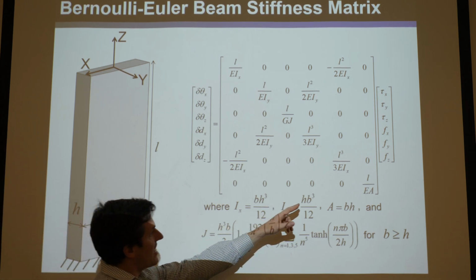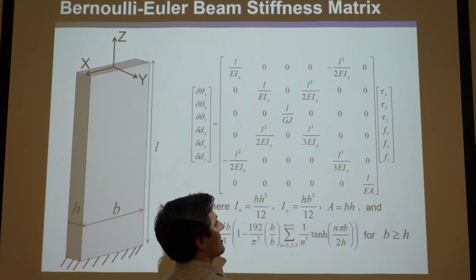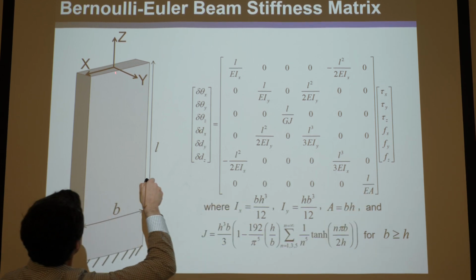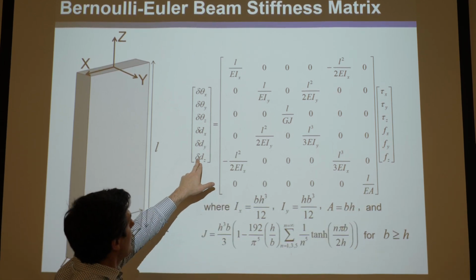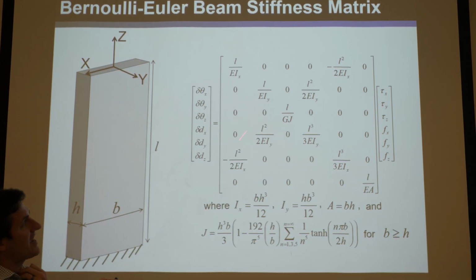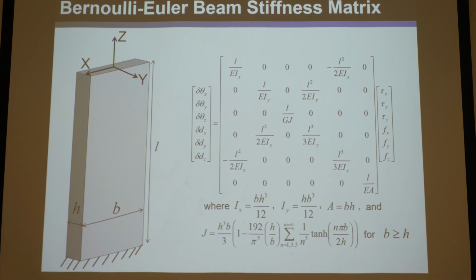Okay, so like for instance, this last one is all 0. The only thing that affects is Fz. We know that's the inverted stiffness. That's the compliance of a beam along the z-axis, and that would be delta dz. Okay, and so check me, make sure my signs are correct, make sure the equations have been flipped and they're in the right location, and everything's being considered.